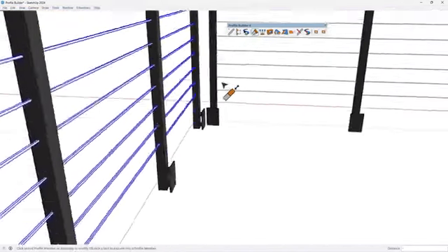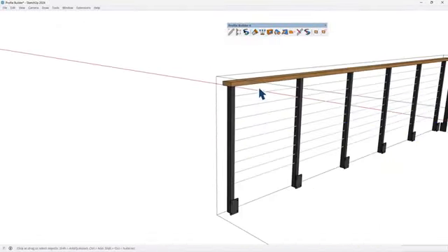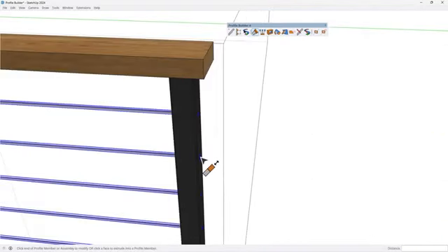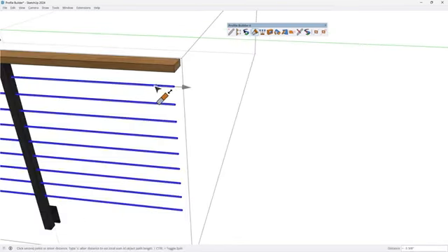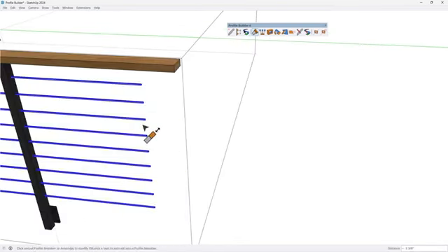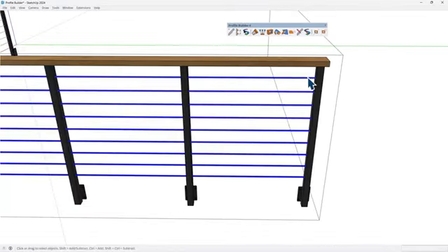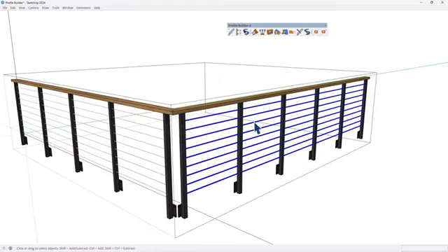So then on this one, I could select these, extend or split, click, bring it back to here. And then if I really want to tidy this up, like before that little air that I had over here, I could again select these, grab that point, which is a little tricky to see because I'm on a bunch of geometry. And if you don't see it, I could hide this real quick. That'll make it a little bit easier to see. So maybe I'll bring it back to there. I'll unhide and then bring it forward to there.